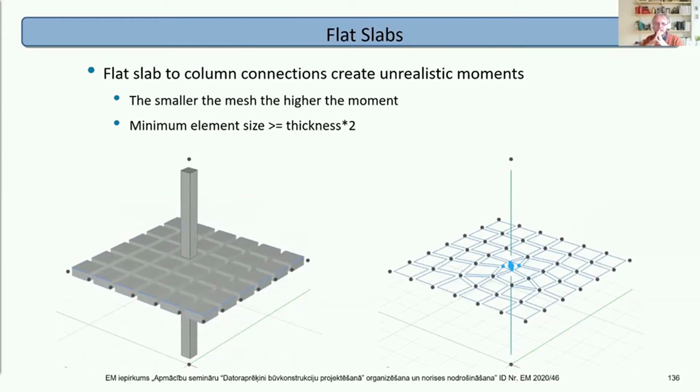Yeah, so as I said, these singularities occur in this case where the metaphors of the 2D and the 1D element break down within the column slab connection. This column slab connection is really three-dimensional, but we're modeling it with 1 and 2 dimensional elements. So this analysis works very well when you're away from the column. Close to the column, it's weak, because the 1D element, whilst if we display the solids it looks like there's a section there, in reality is just a line with stiffness.